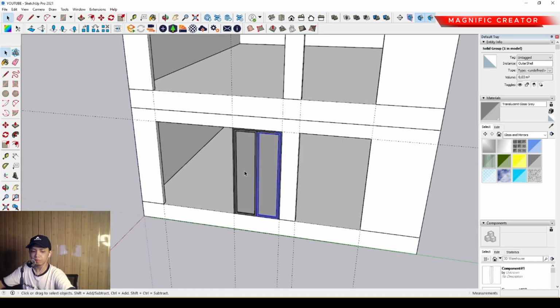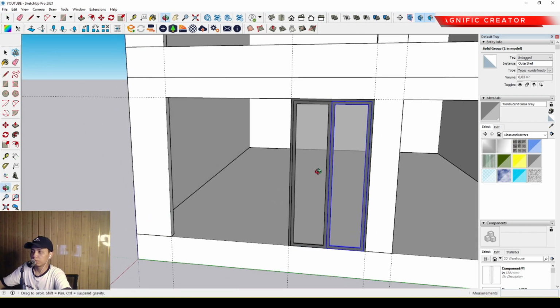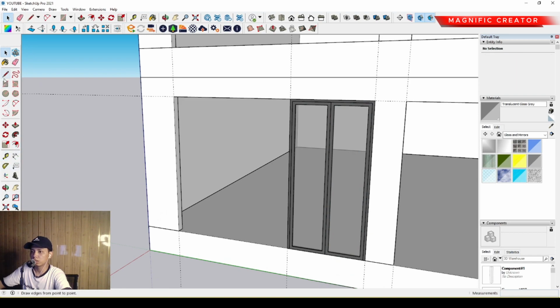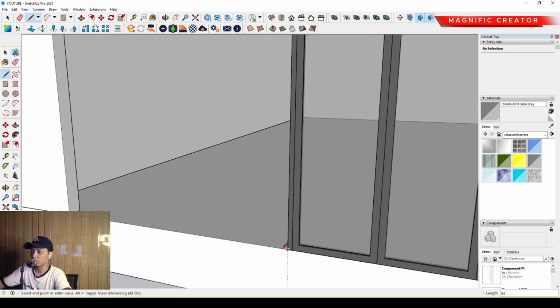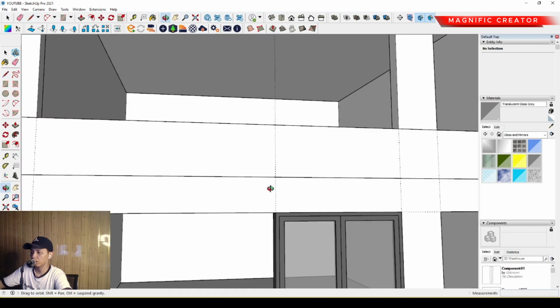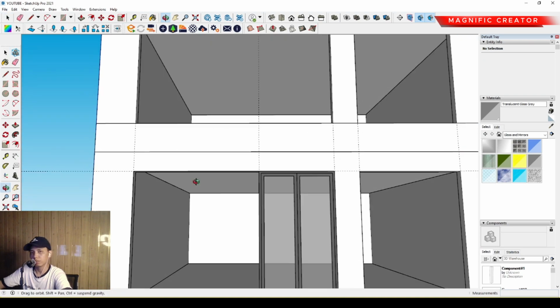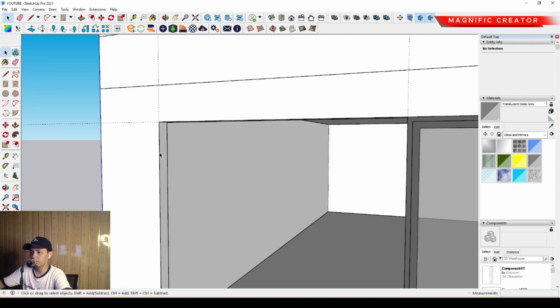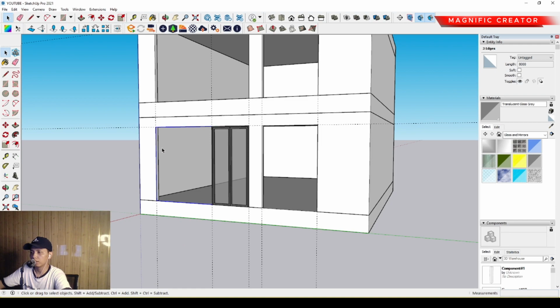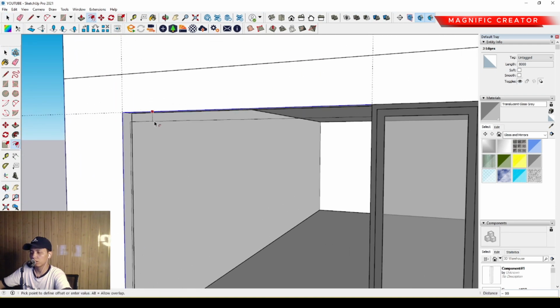Okay, and after that we can make another frame on the side of the door. We can use the line tool, start from here through this corner and through this top corner also, and close in this corner. Okay, and after that we can triple click this triple line anyway. Then we have to offset it inside. We can offset it inside around 40 millimeter.